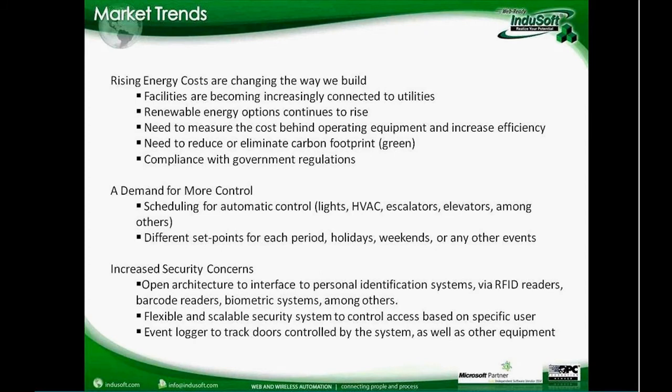They create the schedule and they control all those stores remotely, and they could achieve very significant energy savings just by automatically controlling a few pieces of equipment like lights and air conditioning. They can change the set points manually or even create a schedule to change them automatically over time and plan for holidays, weekends, or any other events.